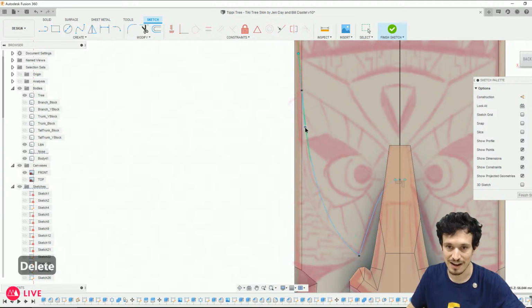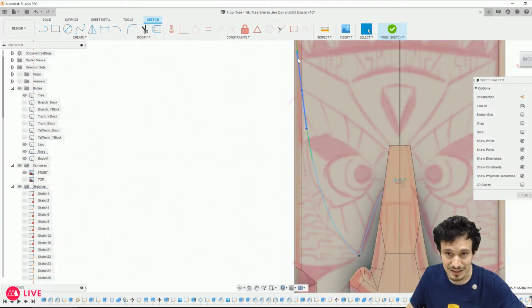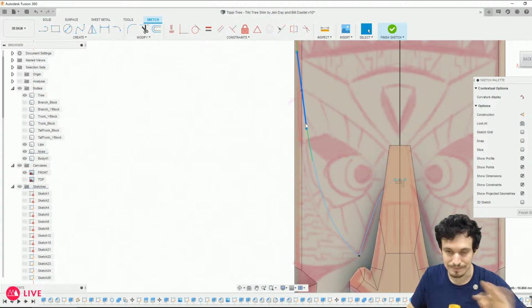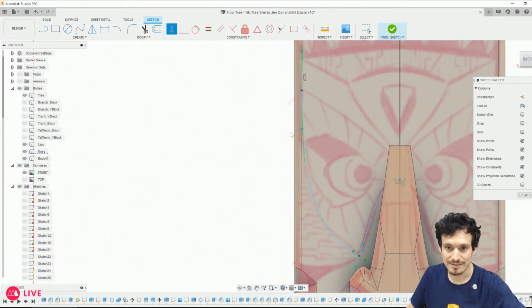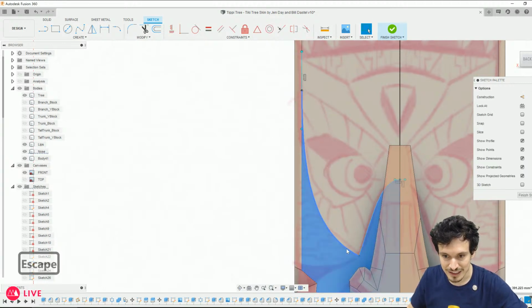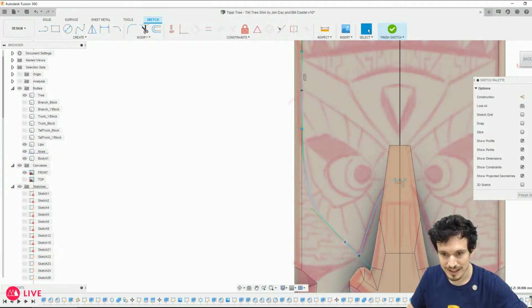Spline's interesting because there's a lot of things you can constrain. You can constrain the points or the actual line or the actual spline. Like, you gotta be kind of strategic about what you're constraining. But look at that. With just 2 points, I was able to follow this whole line pretty smoothly. And I'll do another one here. Wherever there's a point, we start a new thing.